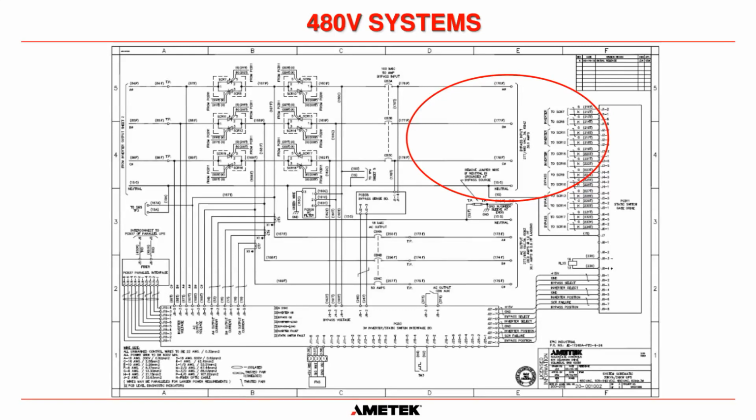the customer and the AMETEK design engineers know that a neutral is being run to the bypass. And that's very important because the inside of our UPS system needs to have a neutral run. And that's so we can sync, monitor things, power supplies. There's a lot of reasons that we need a neutral supply within the UPS system.